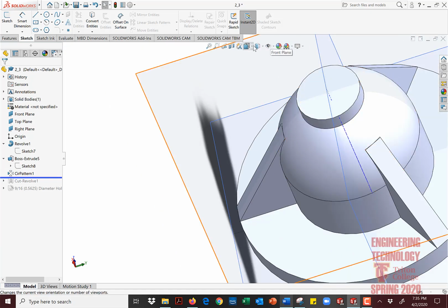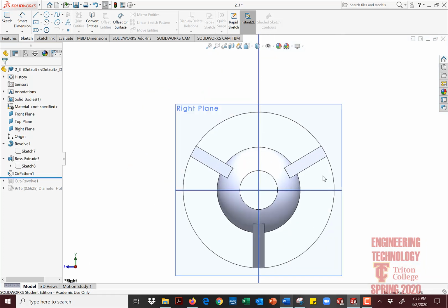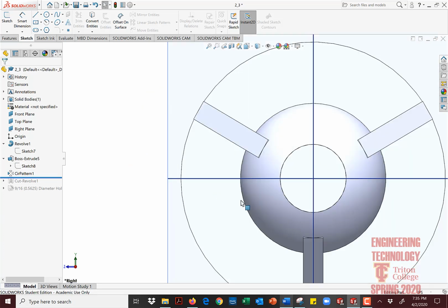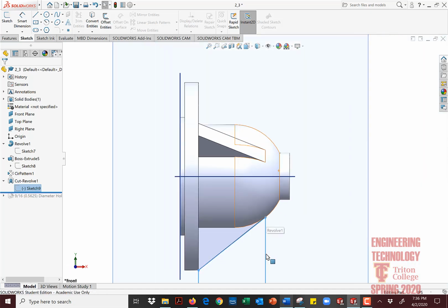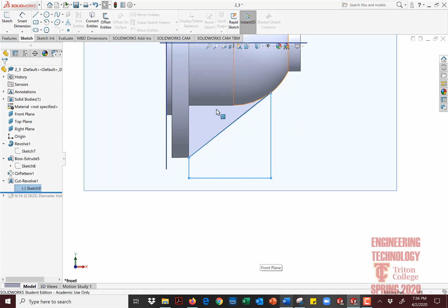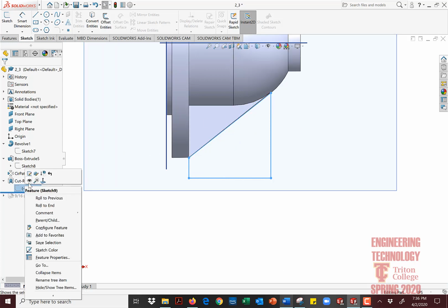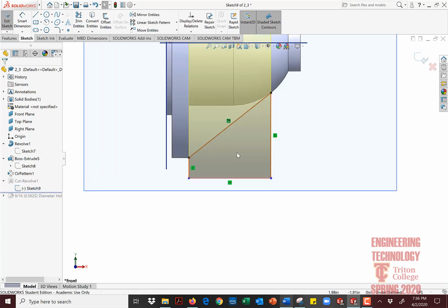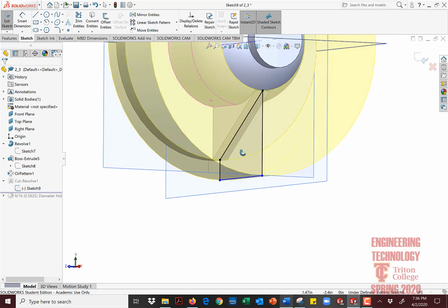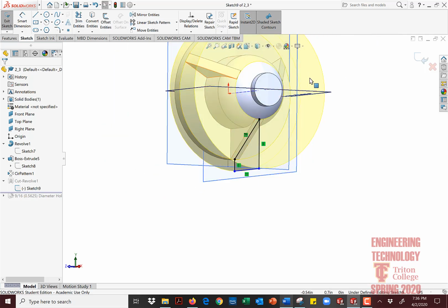We did do a pattern. We did do the circular pattern, so you have all 3, and then we did a circular revolve that wiped out the edges by creating a cutting feature. You see this feature on the outside? This feature was what we used to basically revolve around the center to use as a cutting tool.